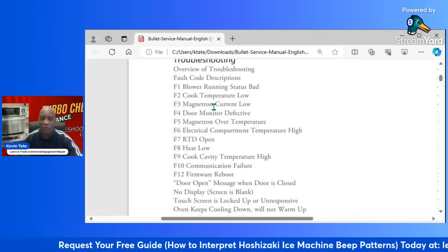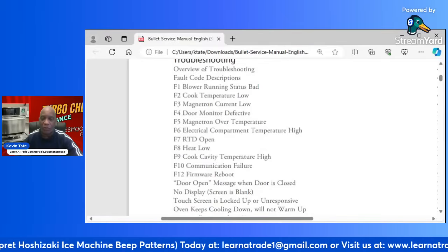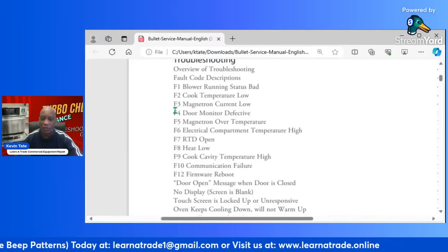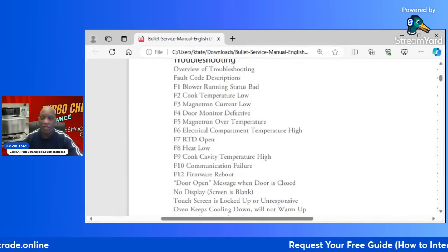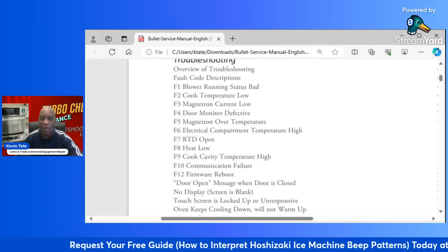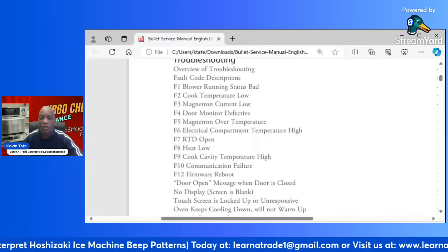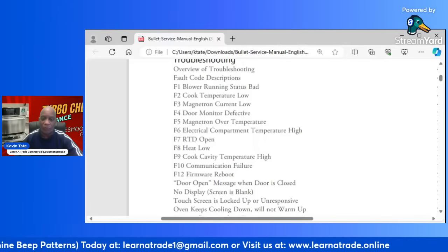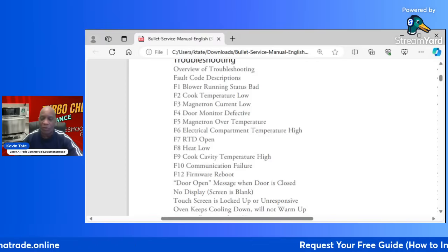These magnetrons are on a 20 amp circuit fuse. So if that fuse is 20 amps and you're getting 6 or 7 amps, the computer is going to know that that's too low. That's not enough amperage to drive both of these magnetrons, and in that case your food's not cooking correctly either. So the machine will go into an error code. Usually after 1 or 2 cycles, it'll go into that error code. If it doesn't sense that 14 amps, it will go into that error code.